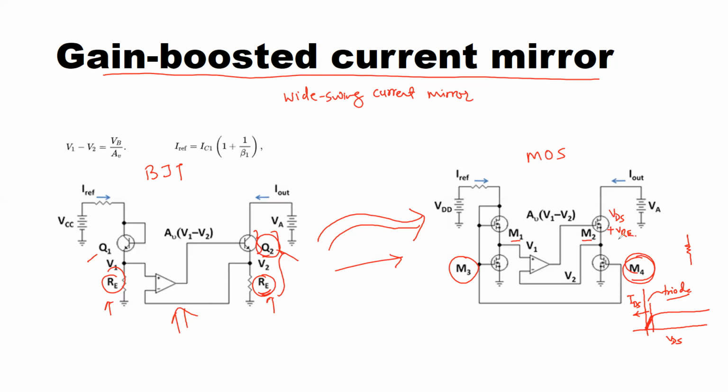VRE right here. So I hope you understood the basics of this video. I will encourage you to use this circuit in your SPICE simulator, pick up the components and the devices from the library, connect them together on the schematic, and make sure your SPICE netlist is free of any errors, including connection errors.